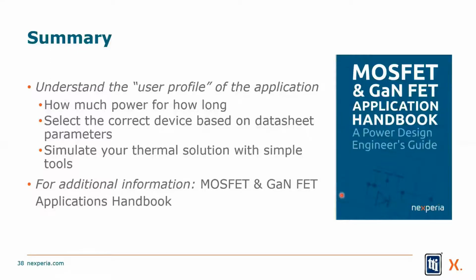If you know those variables and you know how often your motor is going to be used, how long is it on? How long does it have to cool? How much current is it drawing? How much time do I need in an overcurrent situation before I must turn the device off? Once you know all those variables, you can now start building simulations to simulate those environments, calculate the amount of heat that's going to be created inside the device, and then based on that, I can go out to my thermal solution in my printed circuit board and design the optimal solution for it.